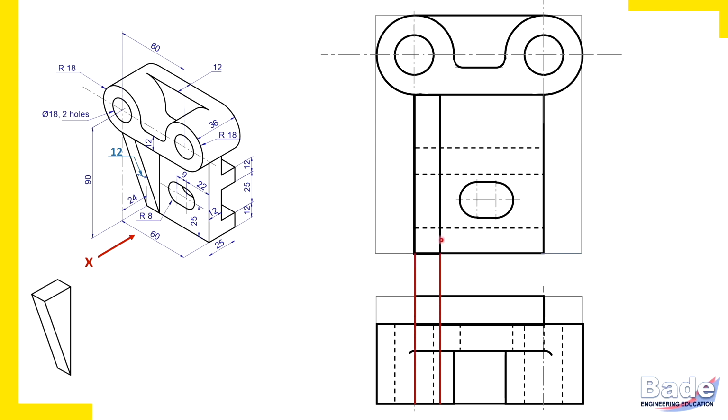Now same plate in the top view. Draw end projectors and up to this part. Watch here. This rectangle is the same triangular plate in the top view. So even if there are so many hidden lines, you are not confused.